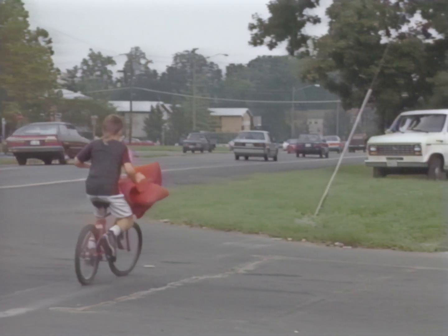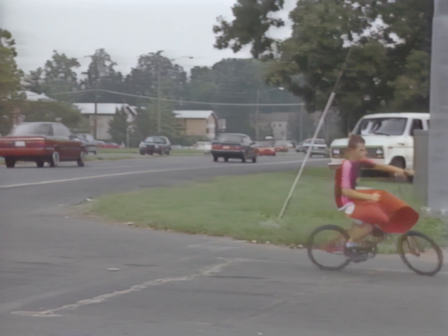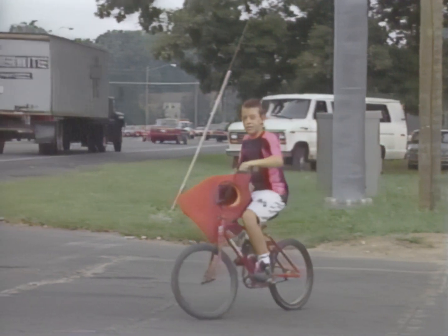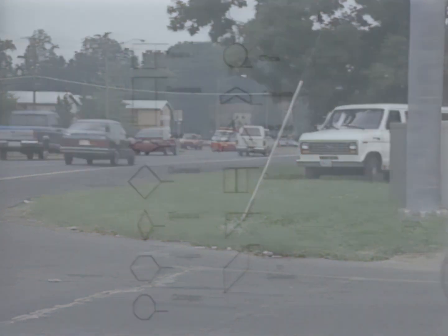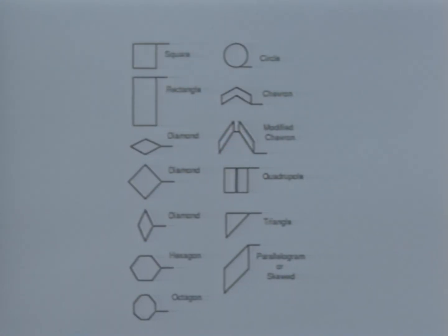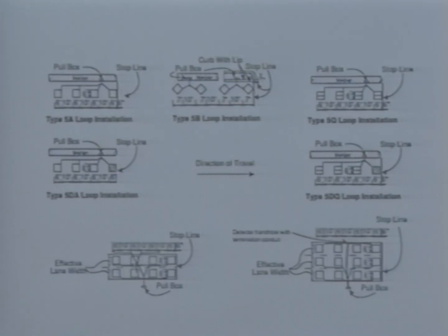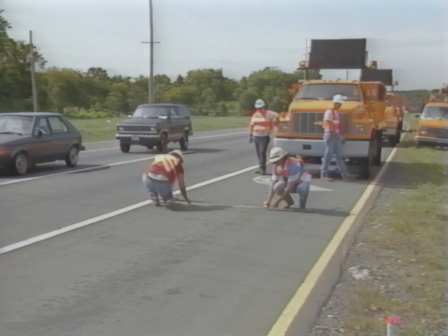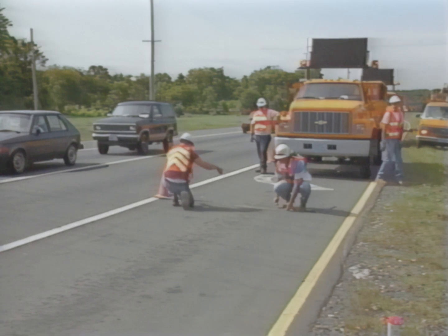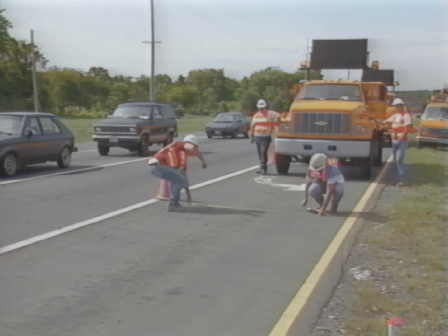Due to the necessity of detecting all forms of vehicles, from bicycles to high-bed trucks, manufacturers have developed quite a number of short-loop designs. Several shapes are in common use, while others are only appropriate for detecting a particular range of vehicles in certain locations. Several states, such as California, specify loop shapes that are acceptable in their jurisdiction. When choosing a configuration, consider the loop shape that will allow maximum detection with the least chance of splashover into adjacent lanes.